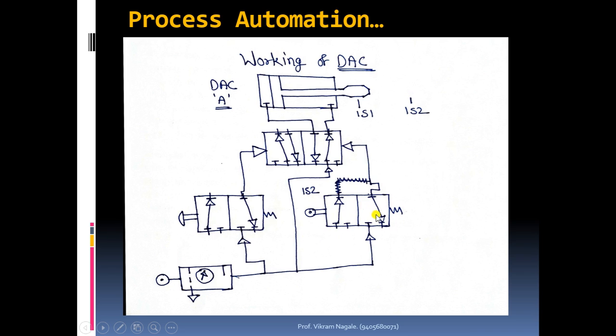Here, obviously, it's a spring return, which means initially the right side block is in active condition, and it sends the air on the output side to the atmosphere through these linings, that is, from port number 3. Now, in order to get output from this valve, that is, to pass the air from the input side to the output side and apply pressure on the right hand side of the other valve, we have to actuate this, or this should get pressed somehow.